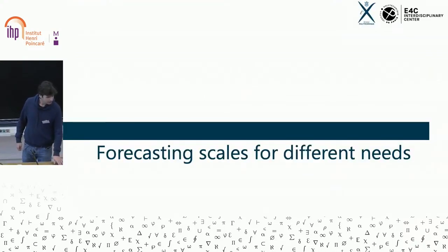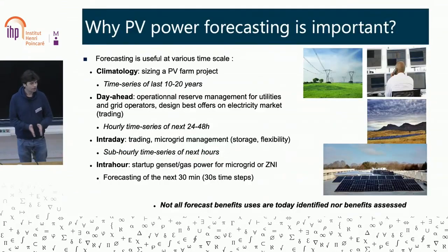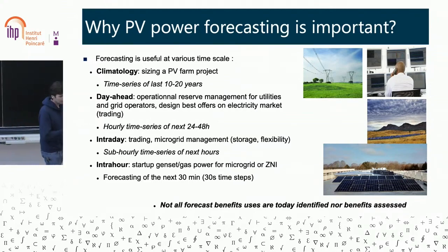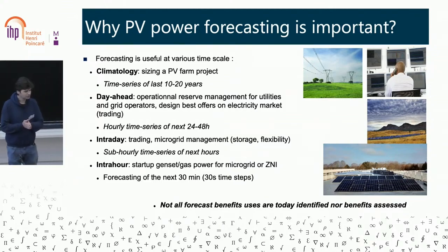So, why is PV power forecasting important? It's important for several applications which cover different geographic scales. The first thing forecasting is useful for is sizing a PV farm project. This is not really forecast. This is climatology. We need it for people who are sizing a PV farm.